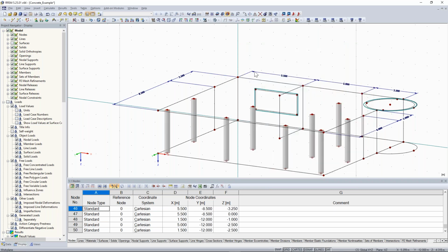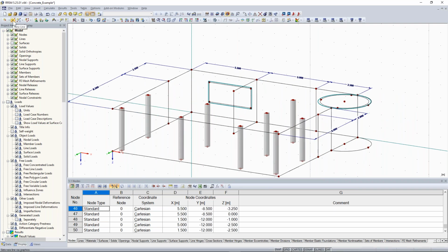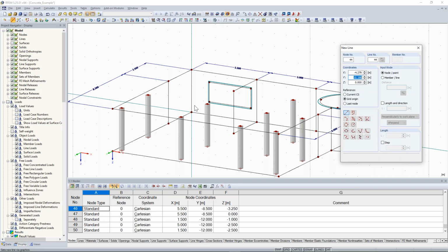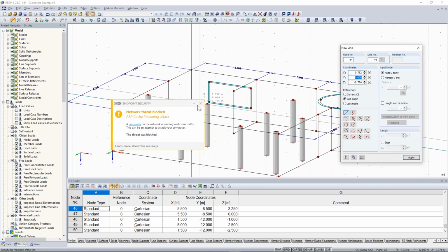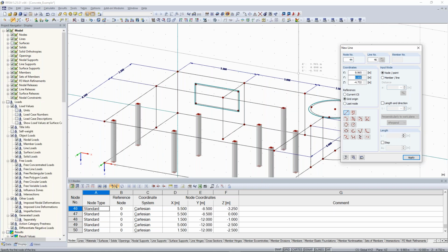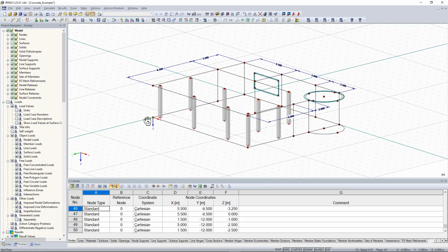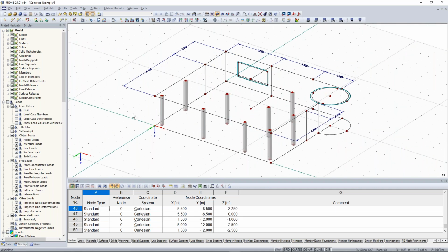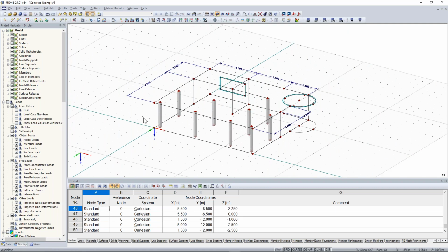And we do it now the same. So when you have a line and you want to transform the line into a member, this is possible. And now we do that in this case. So we create a line because we want to do now a downstand beam. I create now a line from that part to that, and then again to this column. Right click, and now I have here this node. I change the work plane again to my YX plane, and also my grid origin to my set origin.